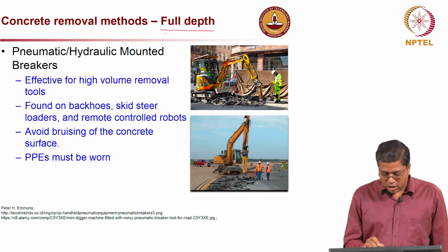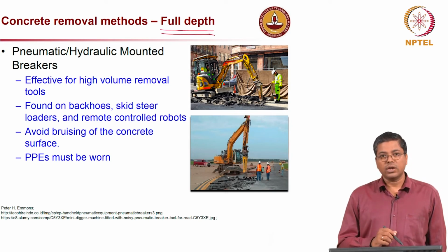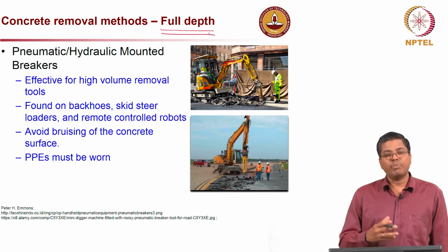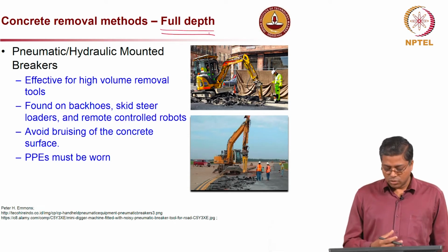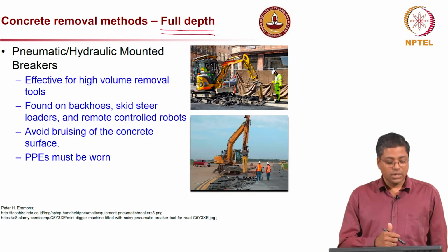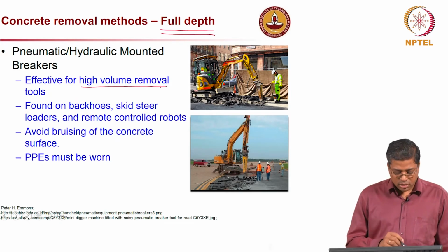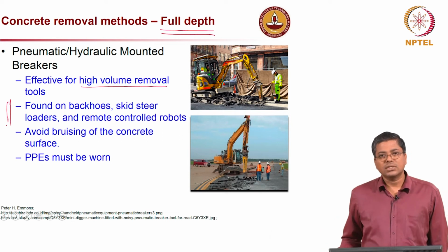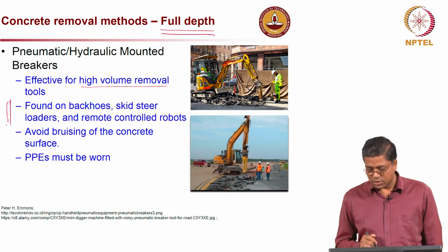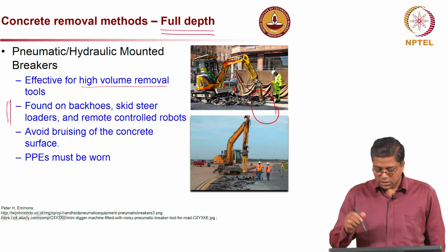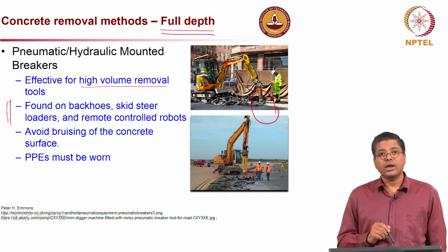Now when you talk about full depth removal of concrete, not just partial depth removal, then you might need more powerful tools, because you are talking about much deeper removal of concrete, which means high volume also, and usually these are fitted onto large construction equipment. As you see in the picture on the right side, there is a bit which is fitted onto the end of this backhoe.